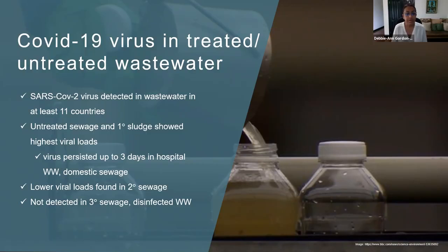The studies also found the virus persisting up to 3 days in hospital wastewater and domestic sewage. So like I said, there were decreases in the loads over the wastewater treatment. Lower viral loads were found in secondary treatment. And in that study coming out of India, in some cases, especially when aerobic treatment is involved, the viral loads drop to undetectable after primary treatment.